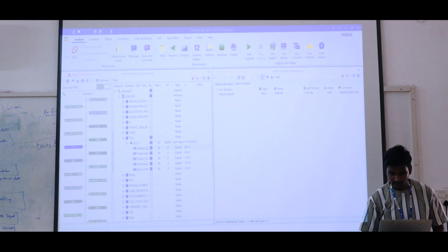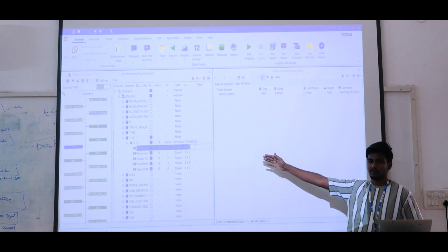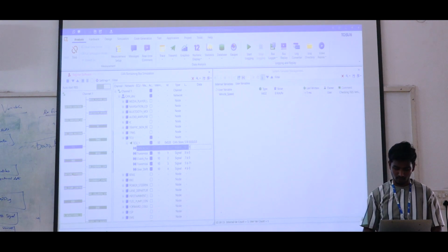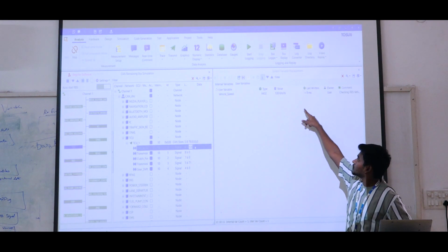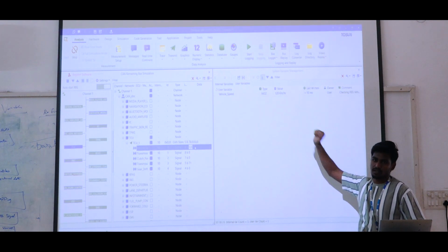Okay. So after this, you have to give the vehicle speed value because now we mapped the vehicle speed value to the system variable. I can give 120. Once you enter the value, you press enter. So now the values change in parallel in our system variables also.